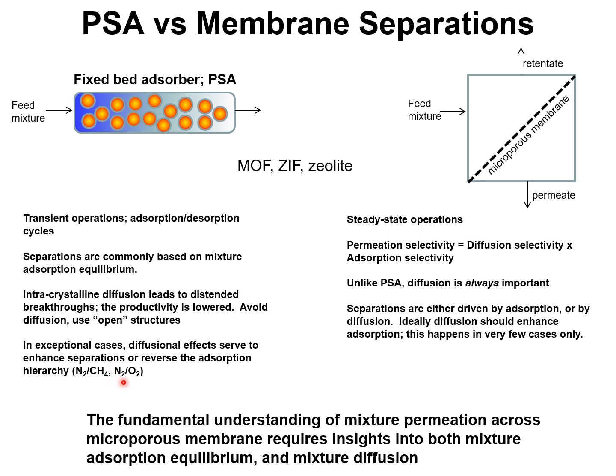And if we wish to prepare or produce purified nitrogen, one alternative is to use kinetic selectivity, and materials such as LTA 4A zeolites, in which oxygen diffuses faster because of its smaller cross-sectional dimension. But generally speaking, PSA technologies are adsorption driven, and diffusional effects are commonly undesirable.